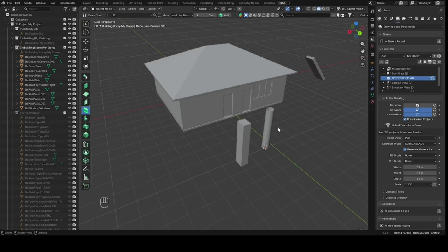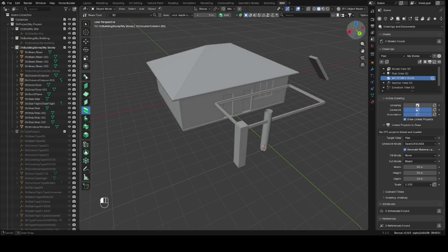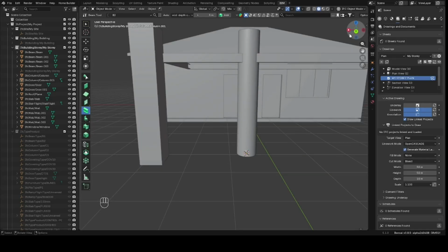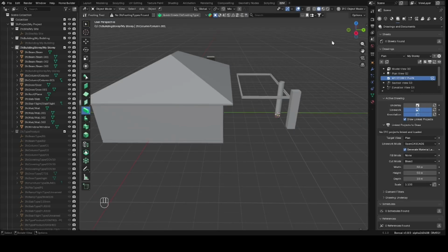So for example, I want to add a simple beam. Just do the shift A, and now this is parametric, so I can constrain it about there. For example, I want Y, X, then I can constrain over there. Then enter, and you can see now you have our beam. It's used either by structural engineers or also when you're creating your object. You have the member tool, the footing tool, the pile tool, so you can play around with these other sections.